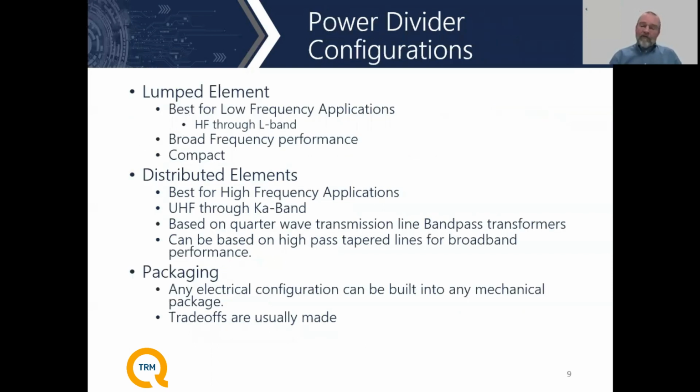Well, basically, and these are sort of generalities as to how we start going into this, lumped element designs are usually best for low frequency applications, HF through L band. They have a very broad performance and they're rather compact.